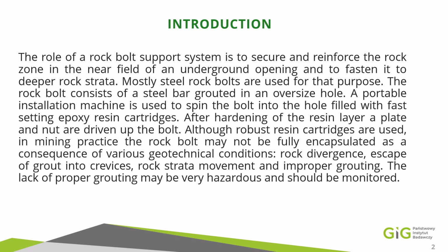Mostly steel rock bolts are used for that purpose. The rock bolt consists of a steel bar routed in an oversized hole. The portable installation machine is used to spin the bolt into the hole filled with fast-setting epoxy resin cartridges. After hardening of the resin layer, a plate and nut are driven up the bolt. Such robust resin cartridges are used in mining practice.